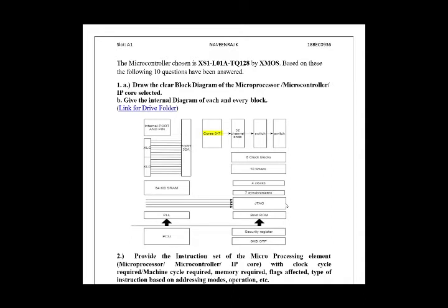So OTP plus security register goes to the boot ROM, and goes to the base of the SRAM, and the program gets executed. So this is all seen as a whole. We don't split it into parts. The security register contains so many features. It will disable JTAG, which we'll see in a few moments. And yeah, OTP security register goes to the boot ROM.